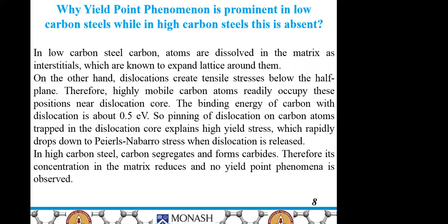In high carbon steels, carbon segregates and forms carbides. Therefore, its concentration in the matrix reduces, which means carbon will not be available for pinning of the dislocations. So that's why no yield point phenomenon is observed.